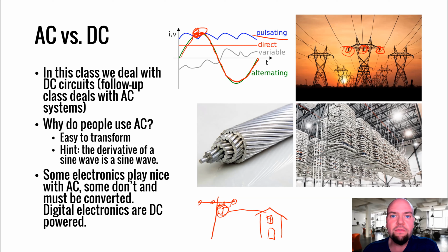And that peak only exists for a brief moment in time, 60 times a second or 50 times a second, depending on where you live. And for a similar brief moment in time, we have this region where we have 0 volts, that's a 0 volt crossing. We have no power transfer at that point. So 60 times a second, we have billions of dollars of infrastructure that's transmitting no power for a brief moment in time. That's not actually fully true because of the way they do multi-phase power. But the idea is there, right? You're not fully utilizing this infrastructure when you have an AC side.